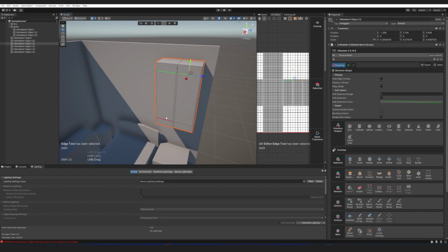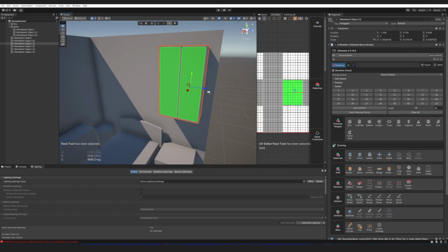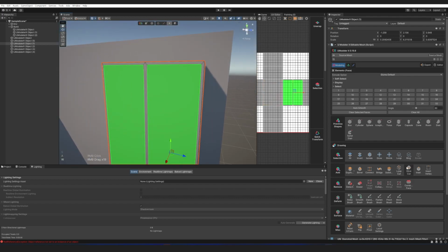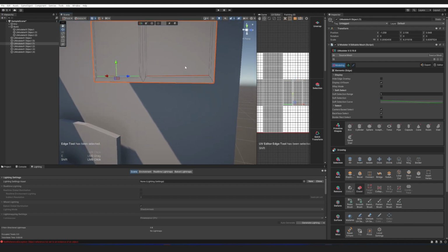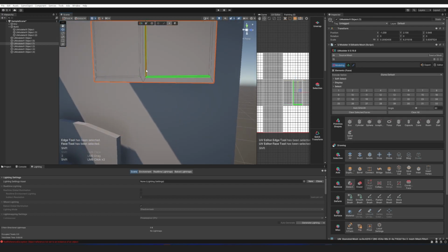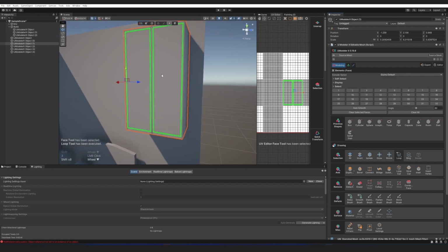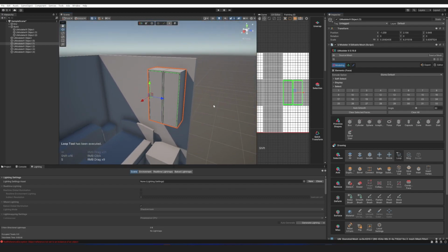Select the line and adjust the left and right spacing. Then, select the inner face and repeat the Inset function. Adjust the spacing by selecting the line and use the Inset function to select the divided middle faces. Using the Select function allows you to quickly select connected faces automatically. Hold the Shift button and push inward to create a gap.